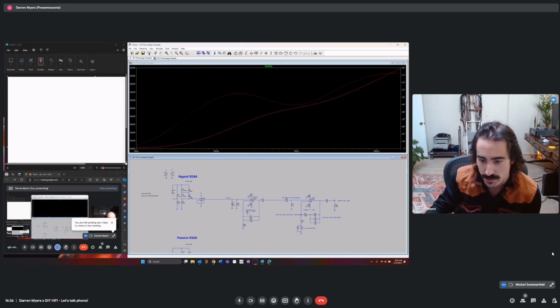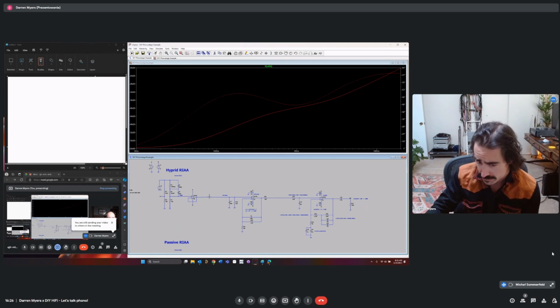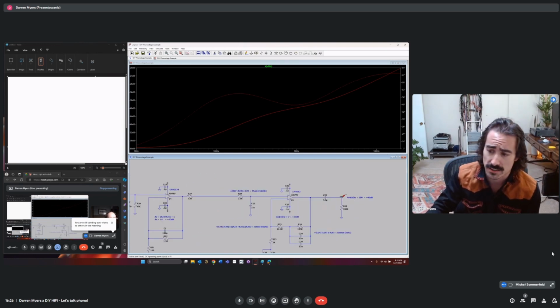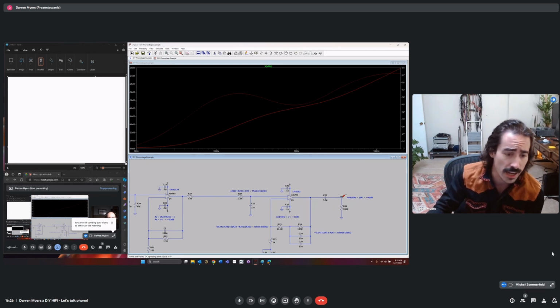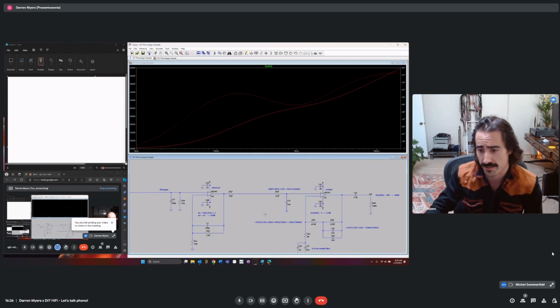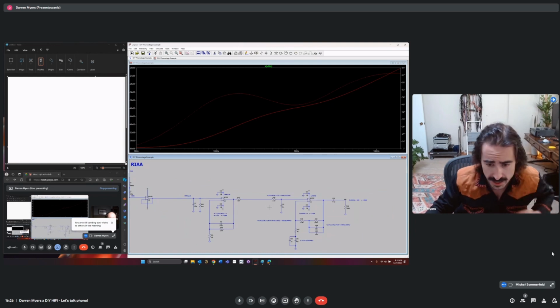We'll come back to that when we're talking about the amplifiers. That's roughly what you're looking at here, up to a gain of 100, which is 40 dB at 1 kilohertz. And this is the way I've configured this phono stage, to have around that gain at 1 kilohertz.